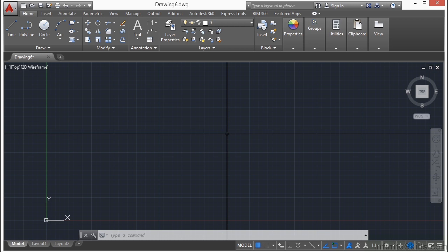Drawing units in AutoCAD are relative. It only interprets the units when you go to print your drawings, or compare it with other files that you've inserted or referenced. Now, it will translate your drawing's units to fit the way you tell it to on your paper. AutoCAD will take your line work and apply it to a scale factor when it prints. It will take the size of the paper you're printing on and scale your drawing objects accordingly.